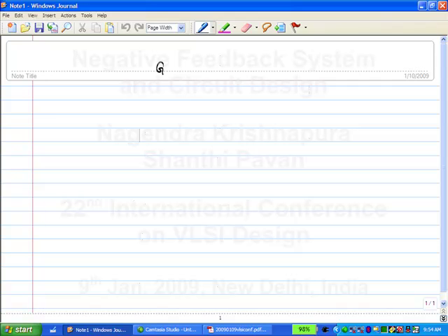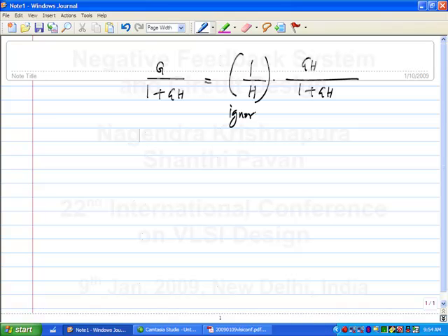So we have G by 1 plus GH, which is 1 over H, GH by 1 plus GH. Now let's ignore this for now. This is the significant part, and you will see that it appears in every feedback system.